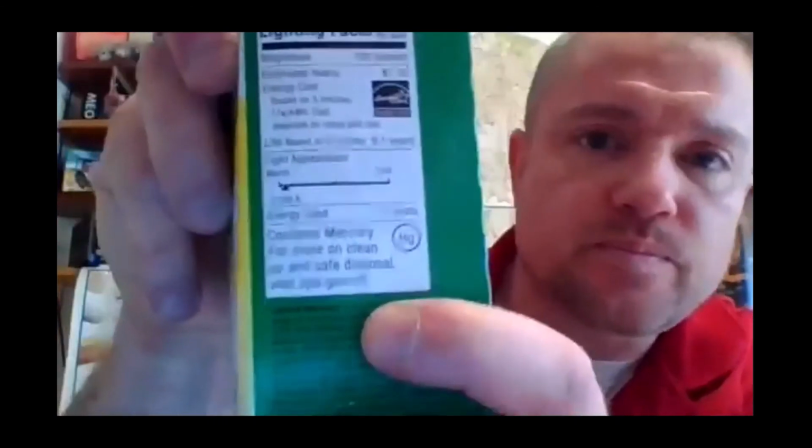So you're reducing wattage, how many watts we use to power our lights. Just as a comparison, an incandescent 60-watt bulb can drop down to about a 14-watt CFL and get about the same amount of light. Now we measure light in lumens and not in wattage. If you look at your lighting facts label on the back, it tells you what type of light you're going to get, and translates looking at light from wattage to lumens. There are lots of different LEDs on the market, light emitting diodes, the same technology that gives us lights in our computers, cell phones, and most cars.